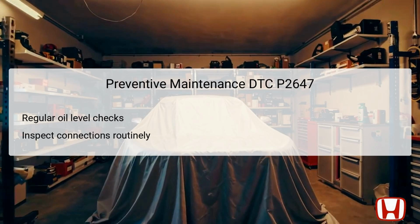Additionally, routinely inspecting the electrical connections related to the rocker arm oil pressure switch, VTEC solenoid, and ECM can help identify any corrosion or loose wiring early on. Corrective actions can thus be implemented before serious faults develop, leading to costly repairs. By adopting preventive practices, you prolong the lifespan and efficiency of the VTEC system and the overall engine.